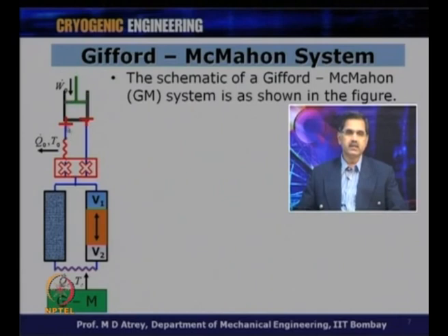That means, with these valves which are built into the system, or the non-return valves, the high pressure and the low pressure side get divided. This was not so in a Stirling cycle. If you try to compare each and every place of the GM cooler, it is very good to understand from this that the output from the compressor was only one and not two. In this case we have two outputs, one high pressure and one low pressure.